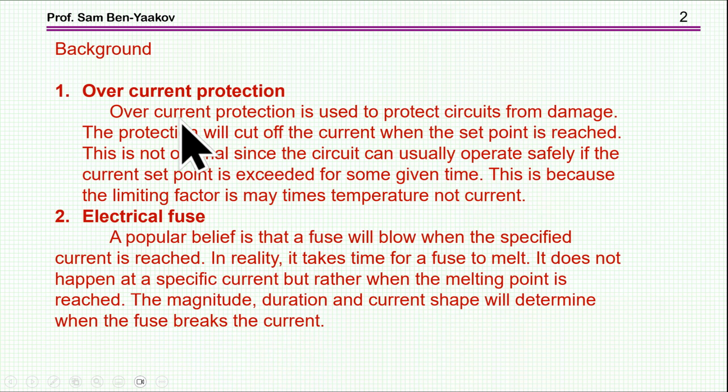Now, overcurrent protection is used to protect circuits from damage. The protection will cut off the current when the set point is reached. This is not, however, an optimal approach, since the circuit can usually operate safely if the current set point is exceeded for some given time.